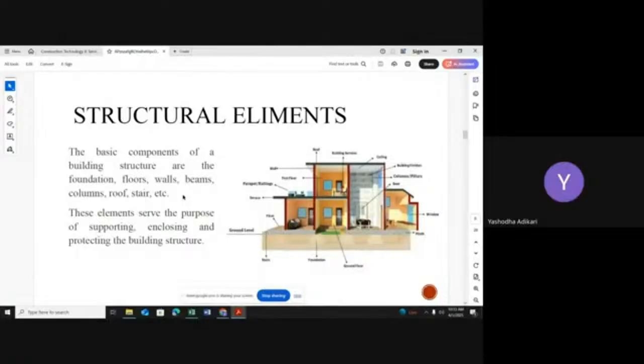Sometimes if you are using very low quality building materials, that also affects building failures. Low quality techniques too. Mainly the foundation type also is affected by soil condition. When you're selecting a foundation type for a building, you have to consider the total load of the building and the soil condition. Those are important. If you're not selecting like that, it creates some building failures.